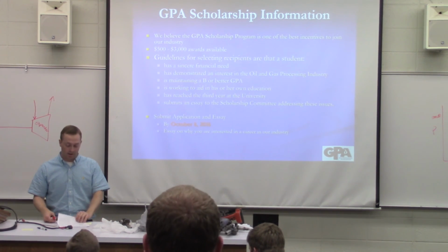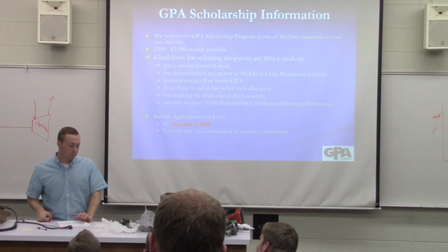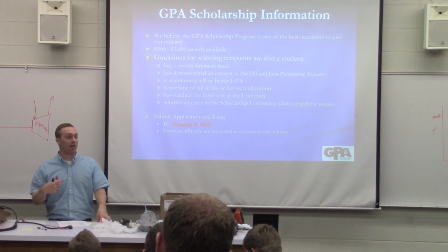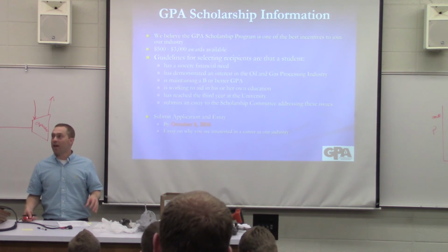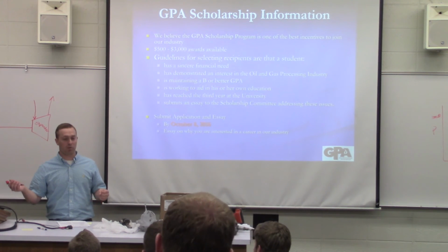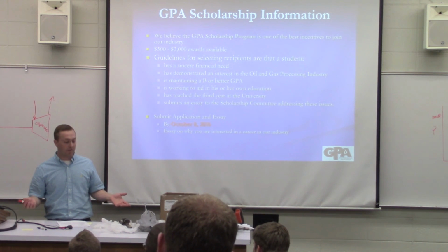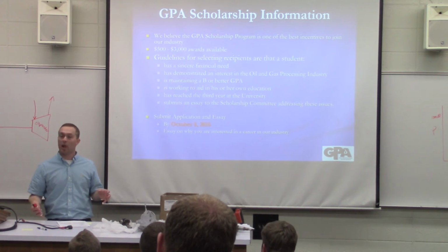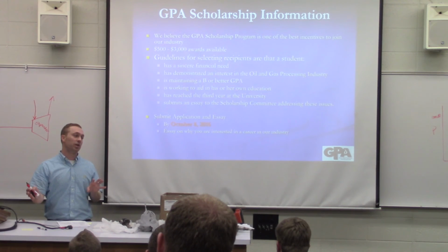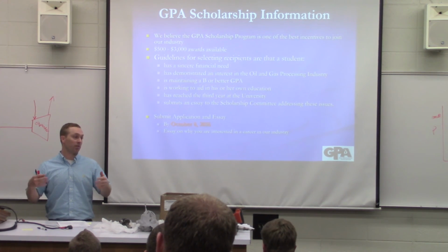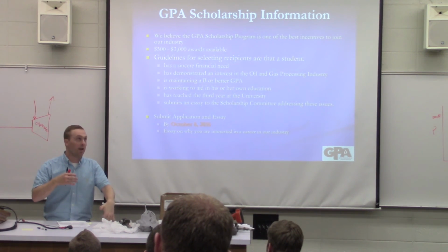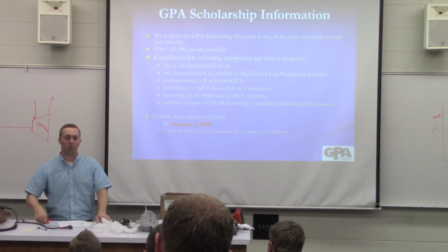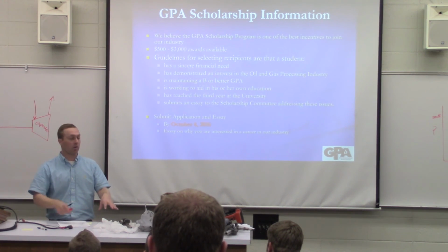One of the interesting things that I got to do really early on with Questar, we still have a refrigeration plant out near Vernal, Utah, and we wanted to expand it. And so we hired an engineering company, and they said the compressors, the propane compressors, which is the most expensive part of the process, you have more than enough compression. So this isn't going to be too expensive, and we can take this from a 180 million standard cubic feet a day plant up to like 240, I can't remember what the number was we were shooting for. And they said, you're not going to have to put in any more compressors.